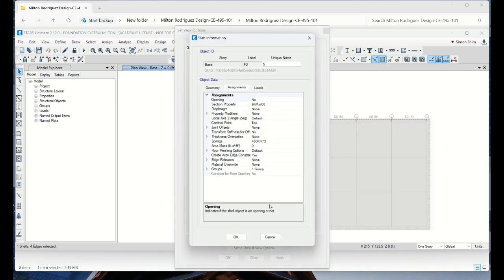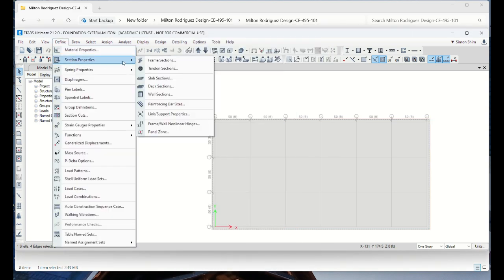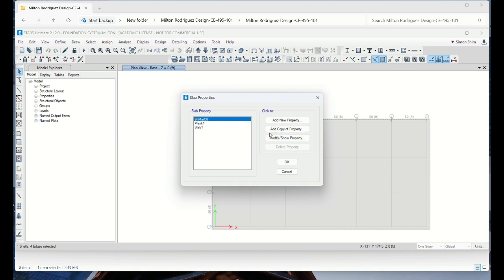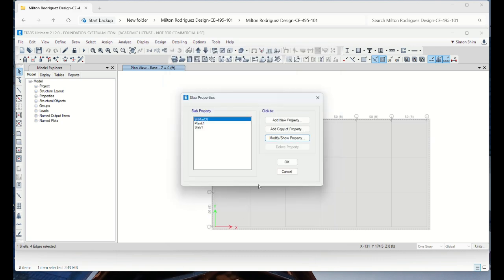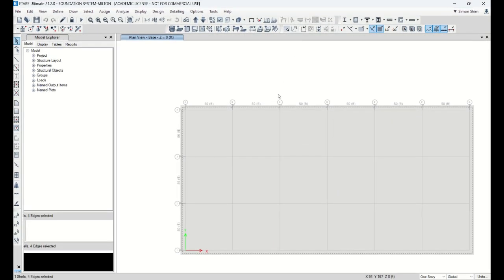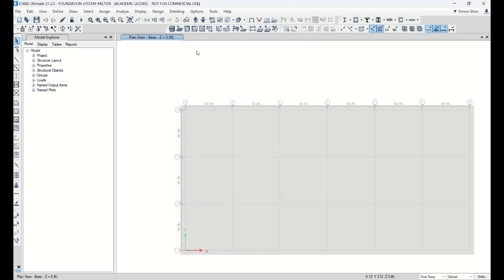You assigned 9 feet mat C6. So I'm just checking your mat, 9 feet, and the 6 means you need to choose 6,000 psi, right? And instead of slab there is a mat element, so okay, you adjusted it. This one had a 6, and you assigned the spring constant as well. We'll take a look at it later.